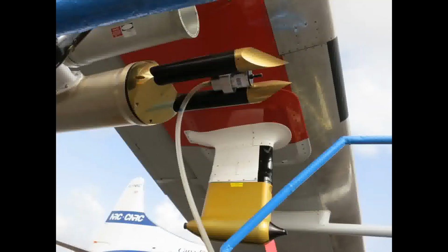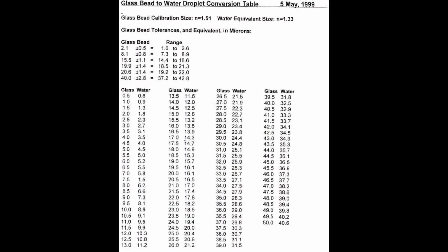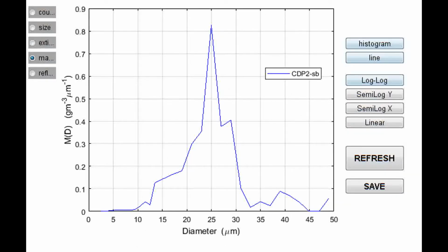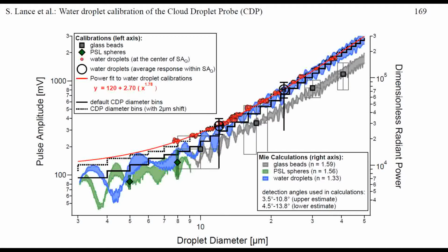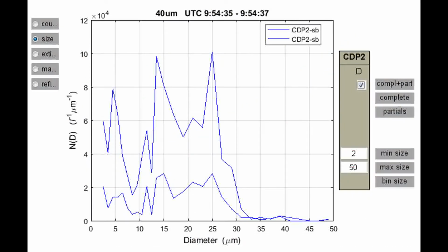For scattering probes, we were limited to throwing NIST-traceable glass beads or polystyrene beads through the sample area. This method doesn't allow positioning in the sample area. The response of the instrument to beads is different than water since the index of refraction is different, requiring a correction factor to be applied to the results. Lastly, the size of the beads is not uniform. They have a Gaussian distribution around the central peak size. If the bins are not properly selected to minimize the effects of the non-monotonic Mie curve, this method won't help you fix the multiple peaks that become apparent in the results.